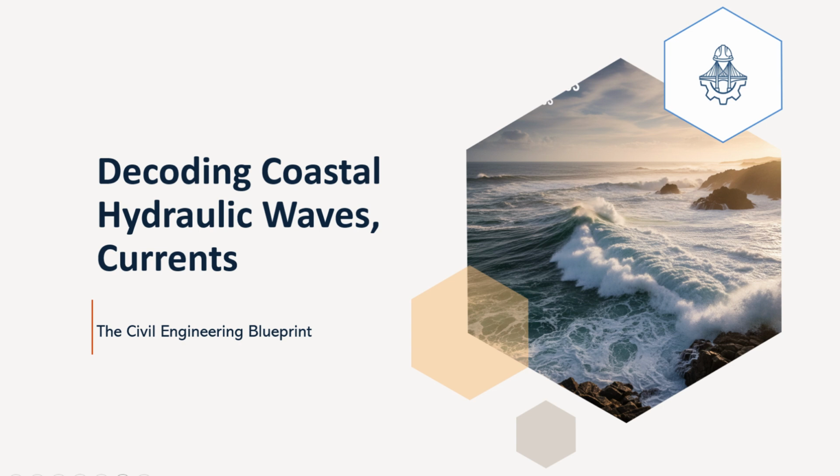But here's where it gets really interesting and unique for water waves. They are actually a fascinating combination of both longitudinal and transverse motions. Individual water particles don't just move straight up and down, or simply back and forth, like in those simpler examples. As a wave passes, they actually move in distinct orbital paths. Picture a tiny piece of seaweed on the surface. It doesn't just go straight up and down. It actually describes a circle as the wave passes. And beneath the surface, these orbits become progressively flatter, more elliptical, eventually becoming purely horizontal right at the seabed in very shallow water.